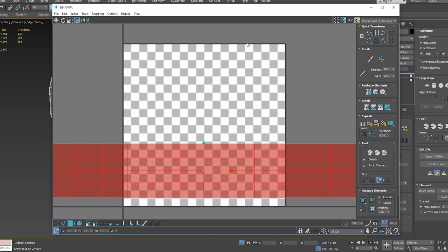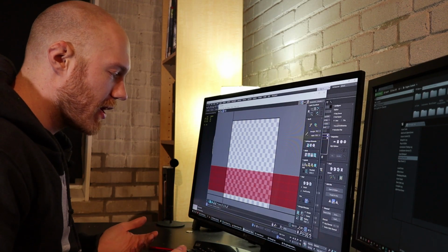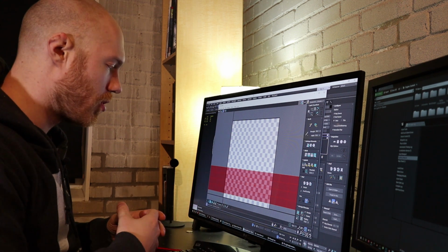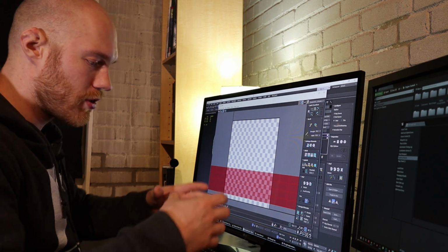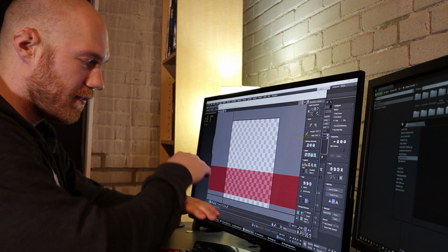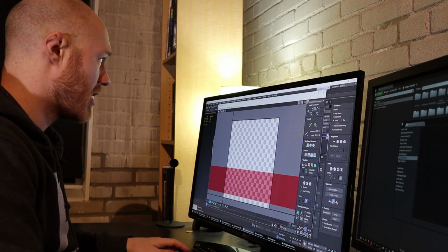the thing with trim textures is you're really going to have to lay out your geometry based on edge loops, and a lot of your UVs are going to be straightened into strips. That way, even though the geometry is rounded and twisted, because the UVs are laid out into a flat strip, it's basically taking that texture and twisting it around onto the geometry. At first, if you've never done this before, it's a little bit of a mental disconnect, because a lot of people think they need to uniquely unwrap their stuff, or they think, oh, it's round, so those UVs need to be round. But using your edge loops, you can slice them and then flatten out all your UVs and straighten things out.